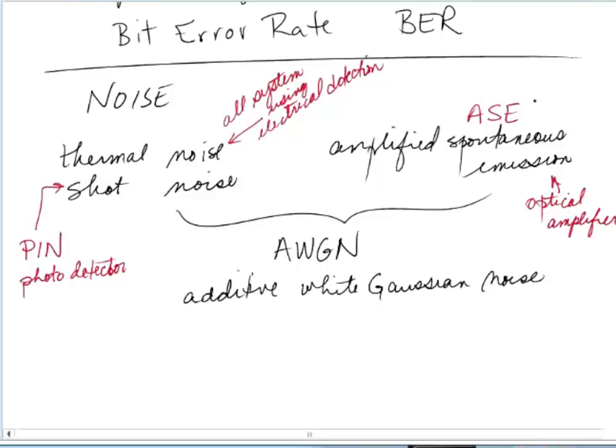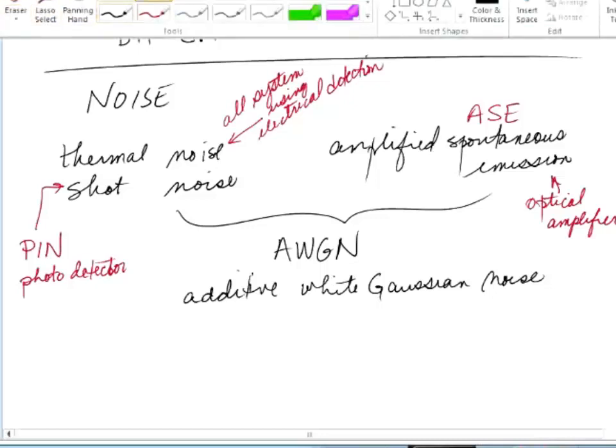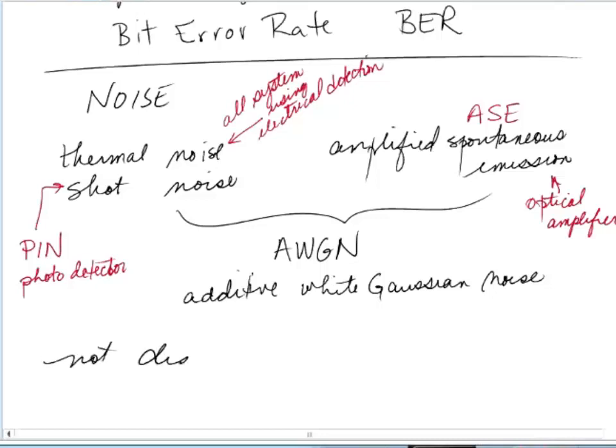And we'd like to know how we can characterize these noises and use them to create a theoretical prediction of the bit error rate. Of course, there are other noise sources which we will not be talking about today. So not up for discussion today would be crosstalk, which is interference across channels. For sure we'll be talking about filtering effects, and the reason that we have filtering effects is trying to avoid crosstalk. So although we won't be characterizing it, we will be discussing issues related to crosstalk.